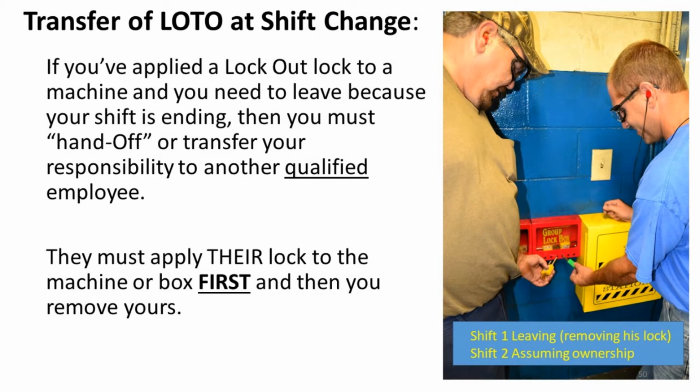If you've applied a lockout to a machine and you need to leave the building because your shift is ending, then you must hand off or transfer your responsibility to another qualified employee. They must apply their lock to the machine or box first, and then you remove yours.